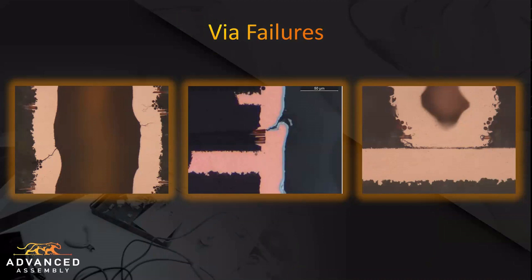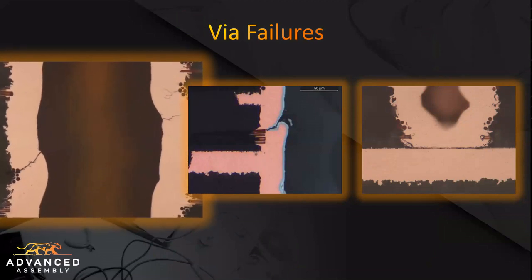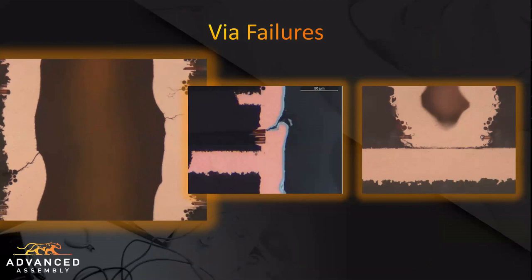Even if your plating is done correctly, high temperature thermal cycling in harsh environments can also cause your boards to fail as well. So I'm going to go through a couple of these different images real quick. This first image in this microsection has significant cracks, and even cracks that are starting to propagate. On the left-hand side of the barrel, you see an entire fracture that's completely disconnecting. On the right-hand side, you start to see stress fractures going into that as well.